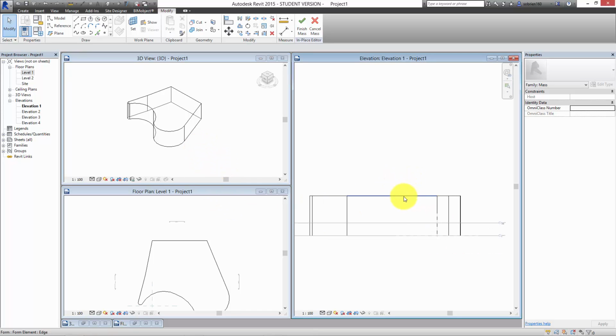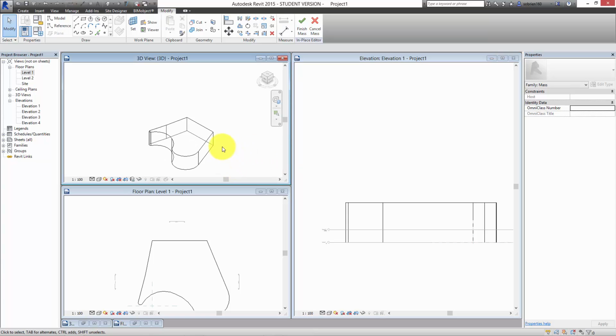Okay, so let's say I want to make the skyscraper a certain height. If I press the tab button, does everybody know what the tab button is? This button on the left here, usually about 3 buttons down. This will allow me to cycle through selection options on the screen here. And this is a really useful thing in Revit, because often if you leave your mouse cursor sitting on top of something in Revit, it'll highlight the first thing it thinks of. So at the moment it's only highlighting one of the edges. If I press the tab button, it starts by highlighting the whole block, then it takes one side of it, then it takes the top side of it, and so on. So now I can choose that I want to edit the top side.